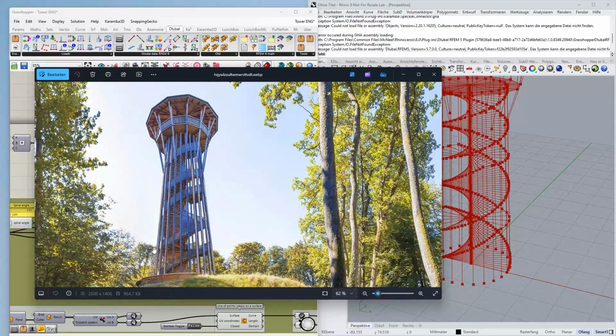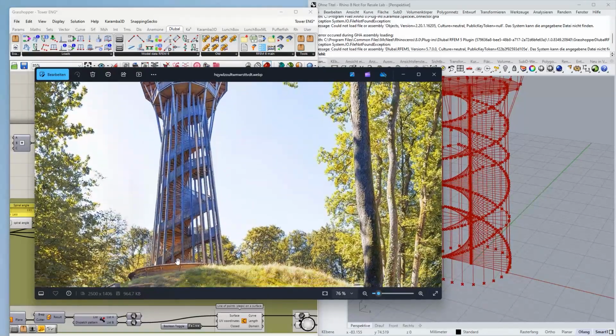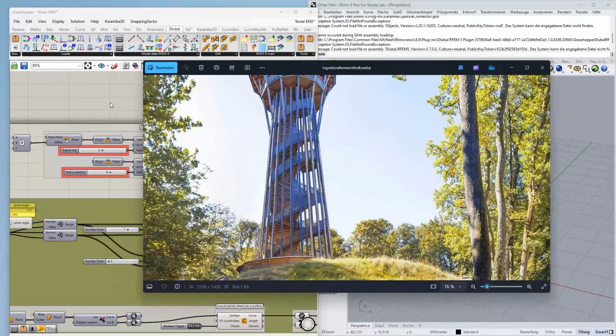And it's like a cone-shaped tower with two independent staircases. So we have a spiral stair up here. It's like helix shaped and it's generated like step beams that are stacked on top of each other, and these step beams are held together with a metal rod in the middle and with the edge beam on the side.